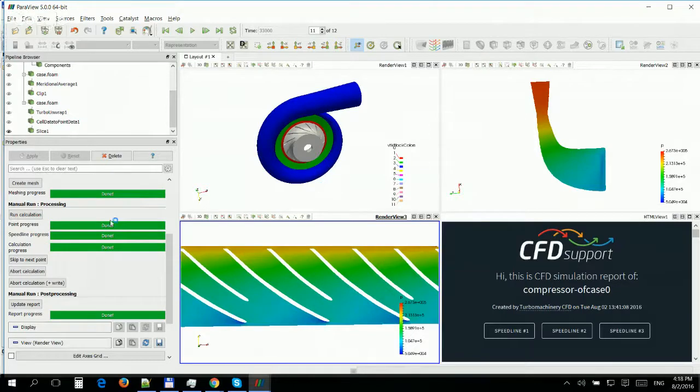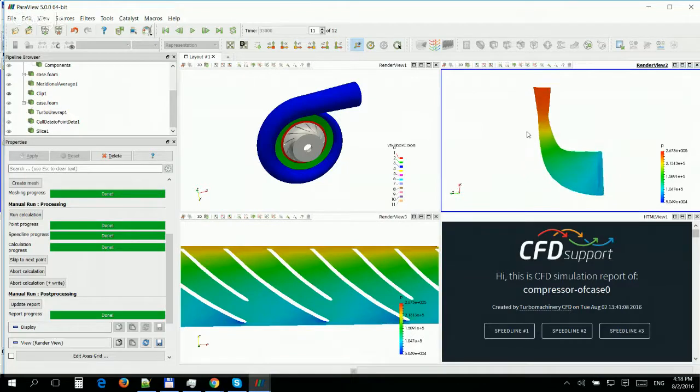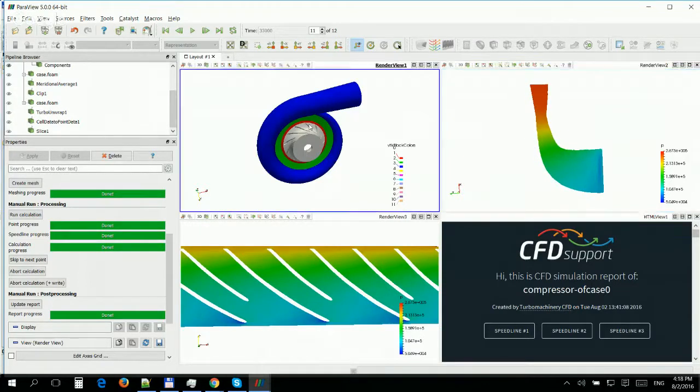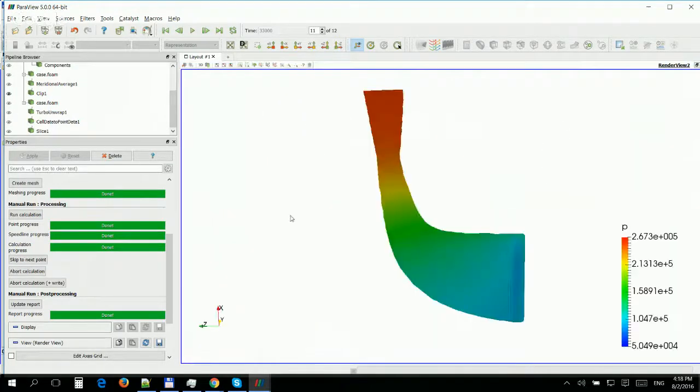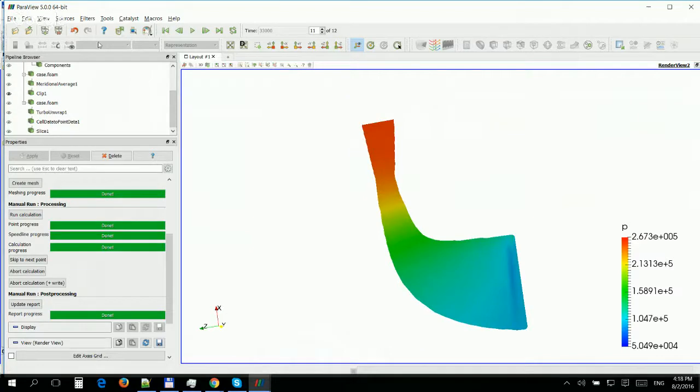After the simulation is finished, you can do the visual post-processing. You know the efficiencies, you know all the statistics, you know torques, you know pressure ratios. Then you can do a special visual post-processing which is called TurboBlade Post. It's again a set of plugins for ParaView where you can watch, for example, the meridional averages of your machine. Yeah, the meridional average of the pressure, for example.